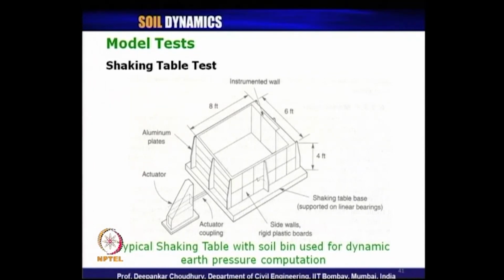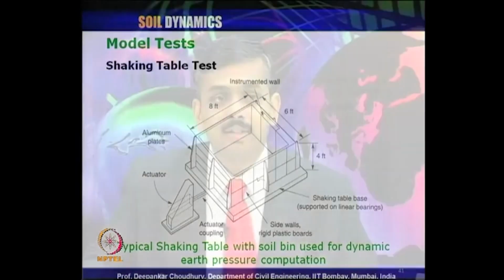The concept of scaling down from the actual prototype or field problem to a small model dimension does not always give you the correct value of the stresses and displacement generated from model to prototype. Why? Because in this case the scaling laws are not that simple, not linear scaling laws.